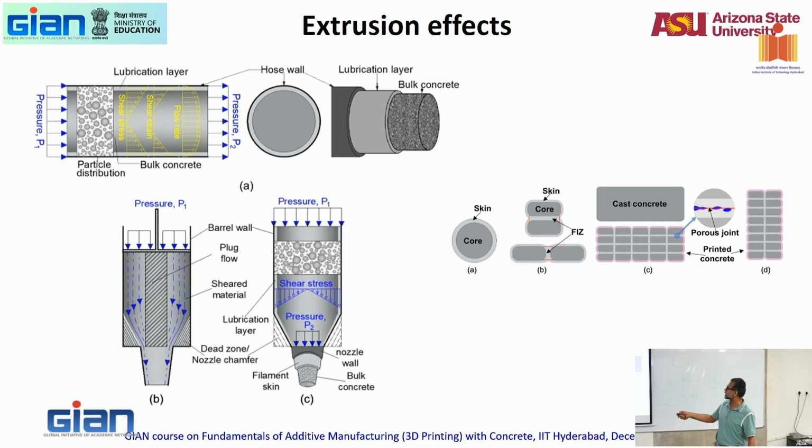So here is a pressure. This is what I showed you. So let's look a little more closely at what we saw earlier. You apply a pressure on your piston. You are pushing this thing through. So you see a shear stress that is in some form because in the center there is really no shear stress, right? It's a plug flow, no shear stress because shear stress is a wall quantity. Shear stress is when you have only a boundary. Remember your parallel plate rheology, you have one plate that is stationary and the other plate is rotating, right? You need one to shear around. Same thing, you need a wall and in the middle you have zero shear stress.